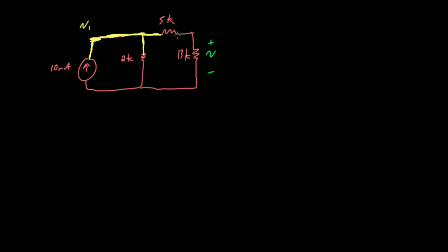Next, all of this clearly has the same voltage, since there's just a wire connecting those two resistors. Let's call that V2. Then we've got one more nodal voltage down here, the node that runs along the bottom of the circuit. We could call this V3, but remember one of the things we have to do in nodal analysis is set one of our nodes to be the ground node. So let's set this to be the ground node.